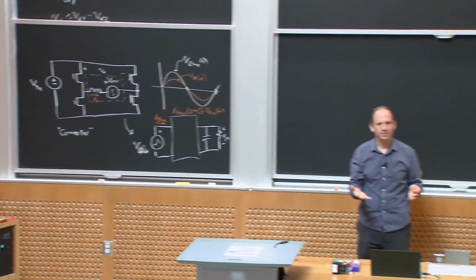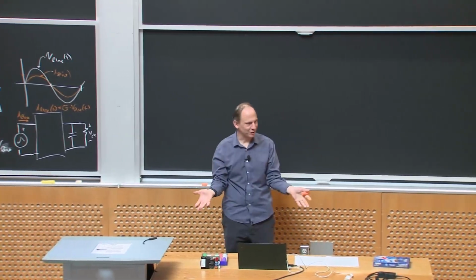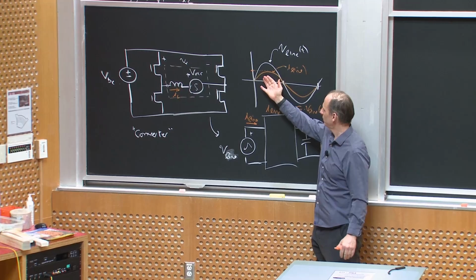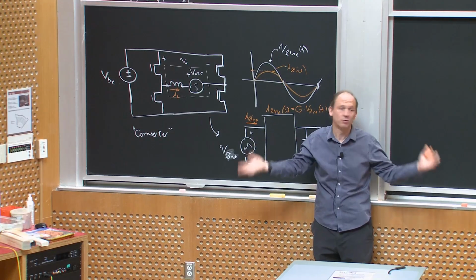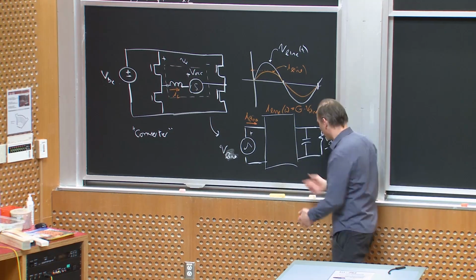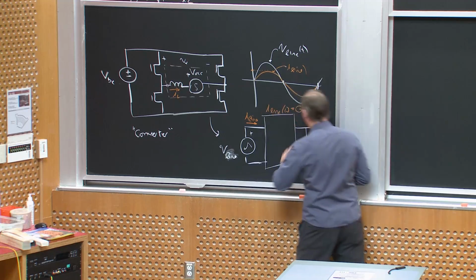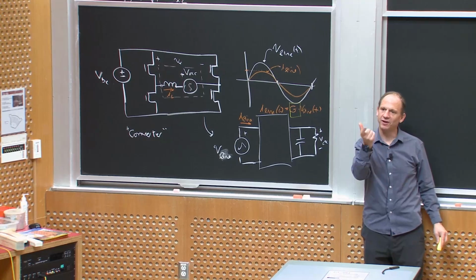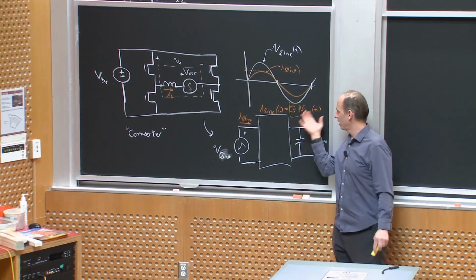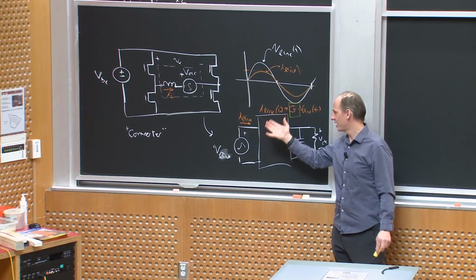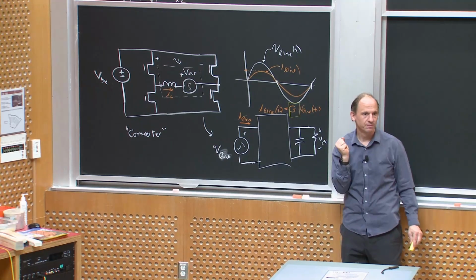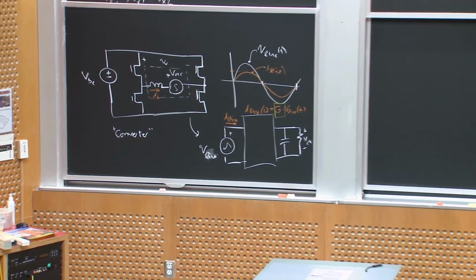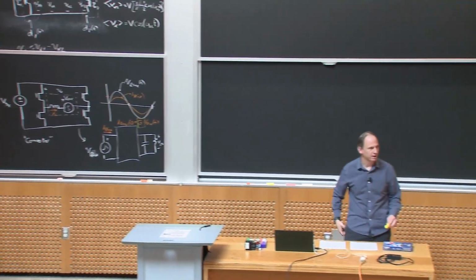So done that way, this is called a unity power factor rectifier because the line current ideally just makes the converter look like a resistor, okay? It's a variable resistor depending upon this constant, right? So as I vary the g to vary the amount of power I draw, I vary the equivalent resistance, but nonetheless, at any given load, it looks like a resistor, okay? Does that make sense to everybody? So that's called a unity power factor rectifier, or a UPF rectifier.